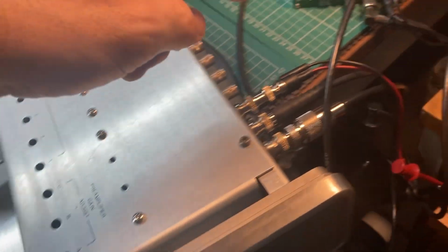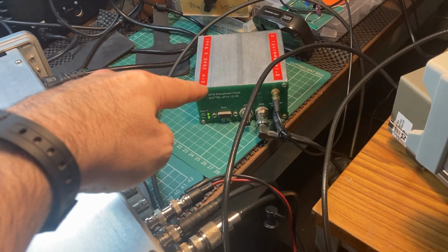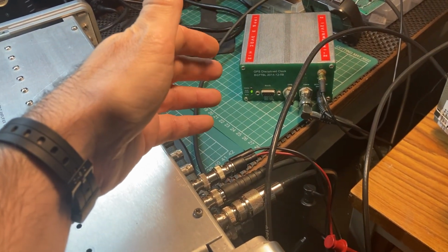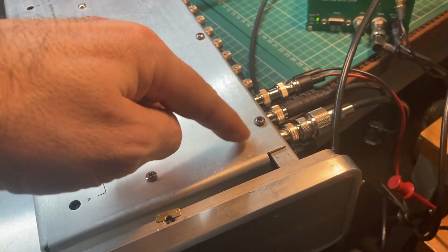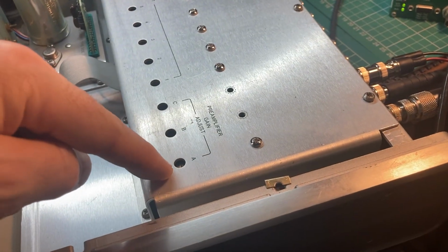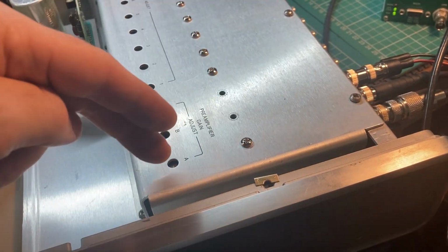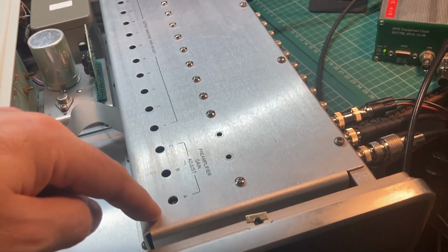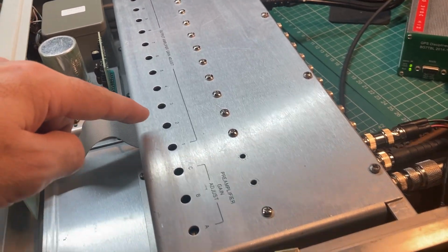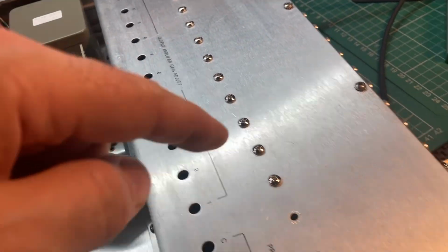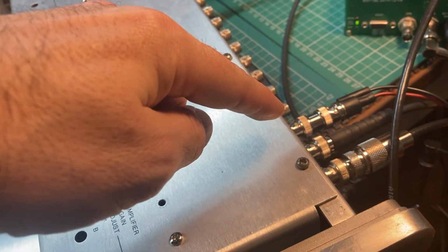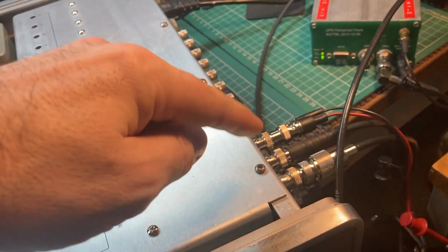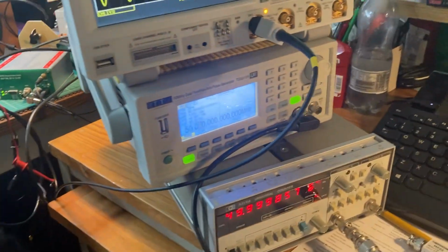So essentially whatever your signal source, in this case the GPS DO, which produces about 6 volts peak to peak, or just over 2.1 volts RMS, put that into the input, and then you can control the gain so that you can kind of buffer that signal to distribute it across the amplifiers so there's no distortion. And then if you tweak the individual gains of all the amplifiers, you can then obviously get a signal coming out, which is a copy of the one you're putting in, but of the right voltage levels for the machinery that you wish to drive.